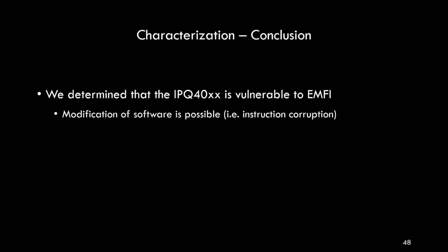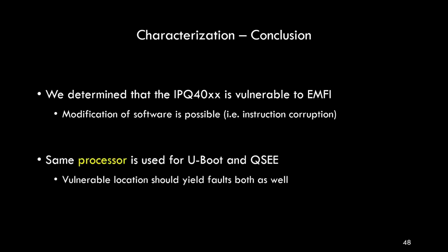So we determined that the IPQ40XX chip is vulnerable to EMFI using our test program. And we also determined that modification of software is likely possible. And we anticipate that this is actually caused by instruction corruption. So we are able to modify the instructions that are being executed. And we make this assumption because this is a typical behavior for ARM-based chips, and from experience, we know that this is likely the case.